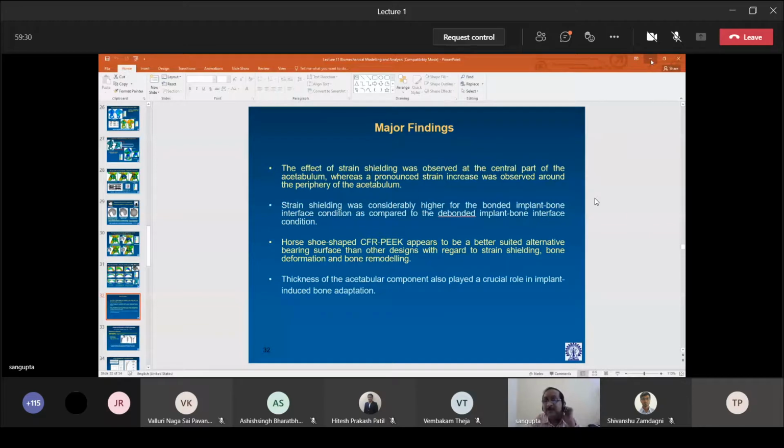That is how to correct the partial volume effect, which is an inherent error. Otherwise you will get a completely erroneous stress-strain distribution, because if you have a low value of E modulus, it will show up in your stress analysis. You will have very high strains on the surface, isn't it? And low stress on the surface, which will never give you true values.